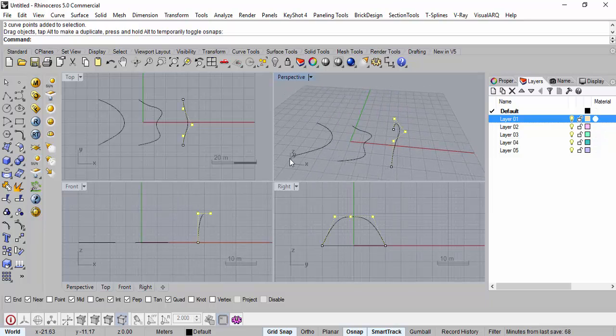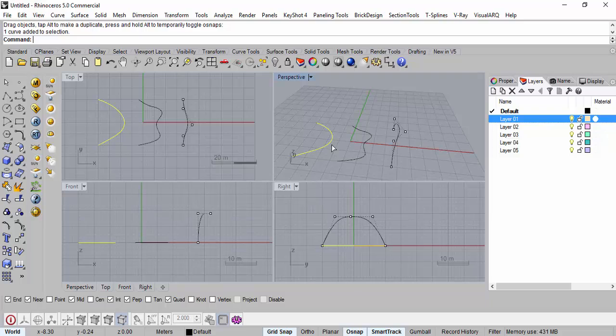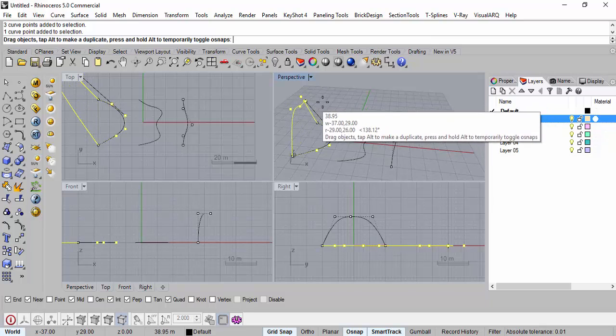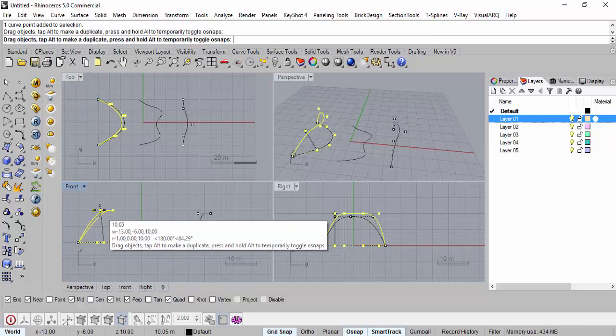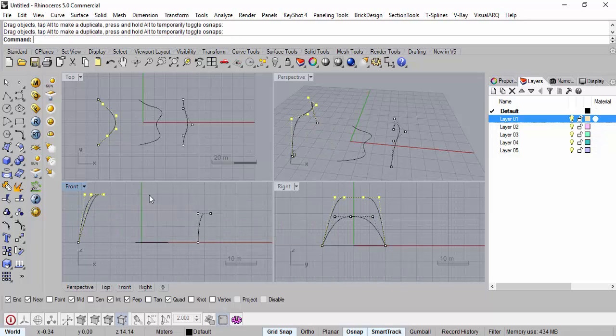So what did I do? I select on this. If I say enter, it will again use the last command, which is to enable the control points. So the control points are enabled. These 2 points are going to be on the ground, right? You want the other 4 points to be taken in the sky or higher up. You select this one by one, and then you are able to move it either from here like this, but it's going to be very approximate, see? Fine? Either from the view, or you can even move it from here. Fine? So this is one way.